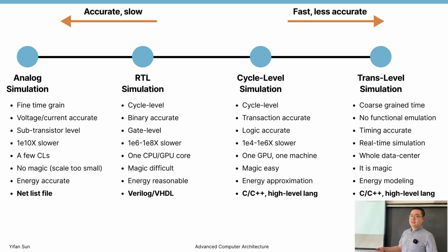You have the RTL level information, all the low level information, but you just implemented this at this level. Okay, so it's accurate. So as I say here, the more you go towards that side, the more accurate, right? But it's slow. On this side, it's fast but less accurate or with less control over what's going on. Okay. So we need to make a trade-off and find the best place that we want to implement our simulation.